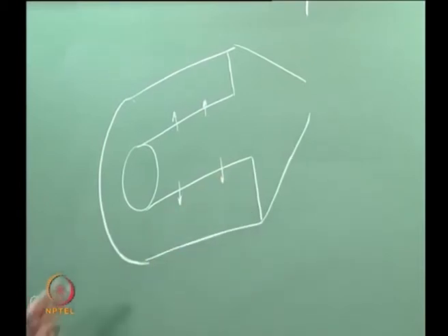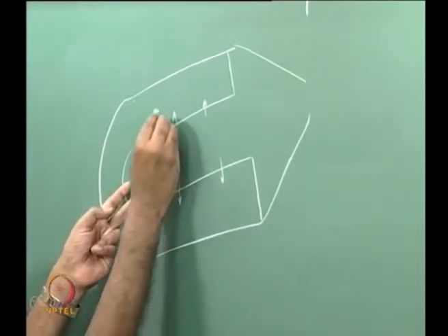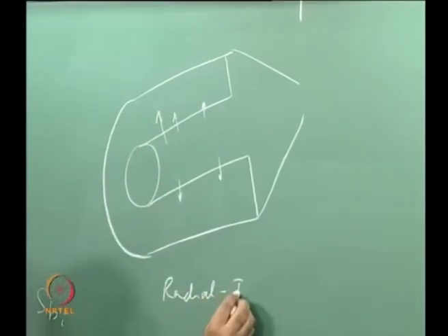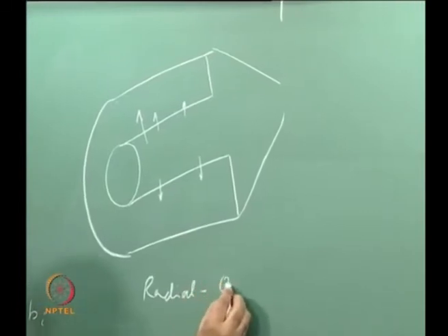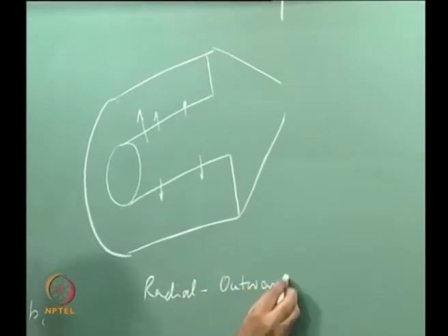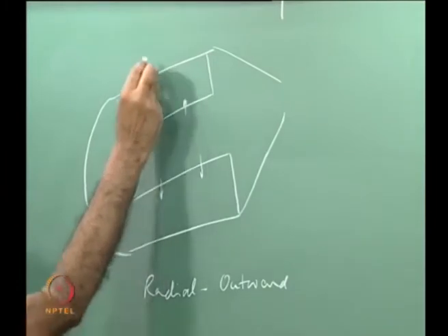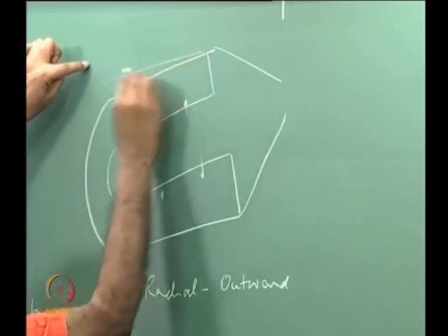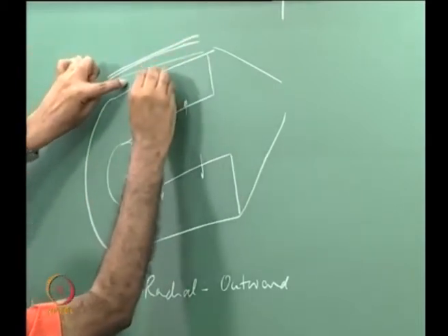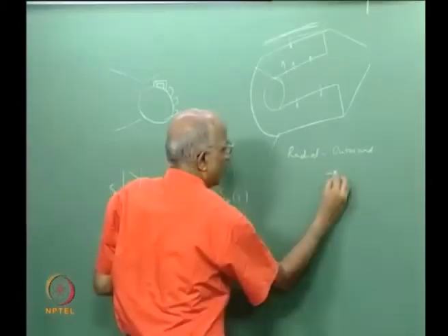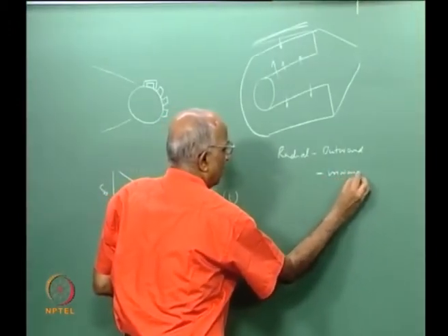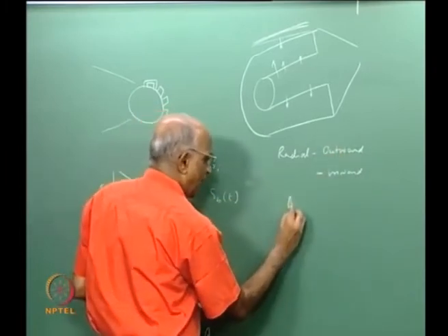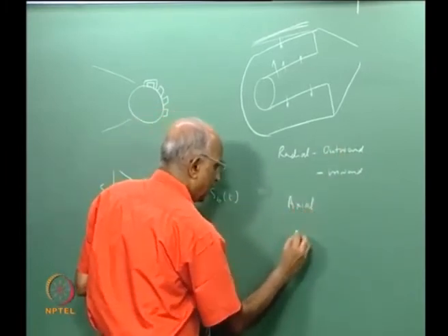and therefore my burning surface area, the burning is radial and it is outward from the center. Burning takes place from the inside surface to the outside. If I ignite it on the outer surface, maybe I have, let us say, a gap and the case is insulated, I allow it to burn inward, therefore I say radial inward. This was progressive, this was regressive. We also had axial burning. By axial burning, what did we have?